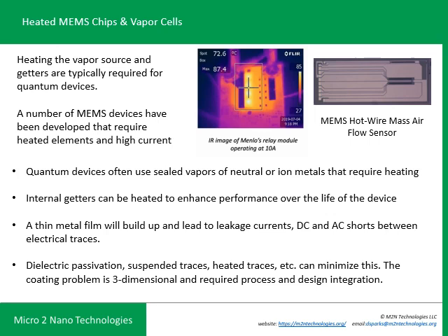Micro Menlo has developed a MEMS-based switch for power devices. They have a vacuum cavity. It's an all-glass chip stack with through-glass vias. They pump a lot of current in there to heat it up. And they've been able to develop a pretty robust, reliable technique for making these types of chips with heaters.